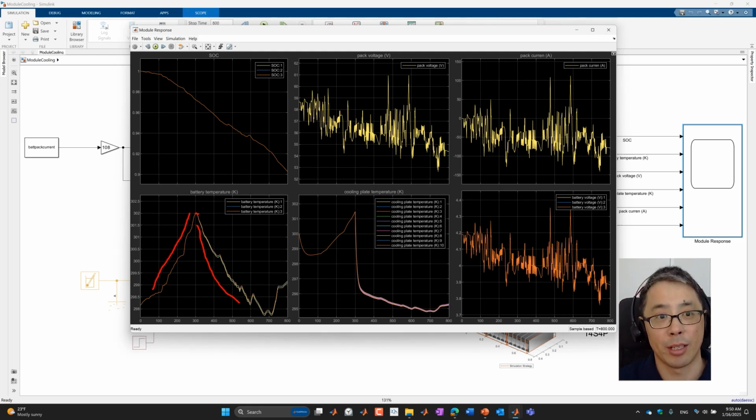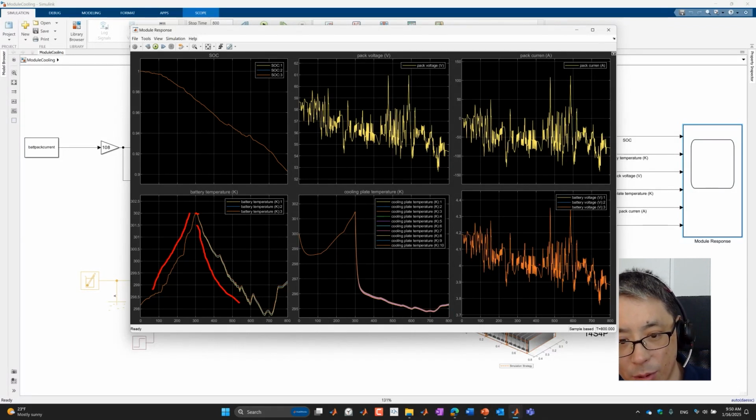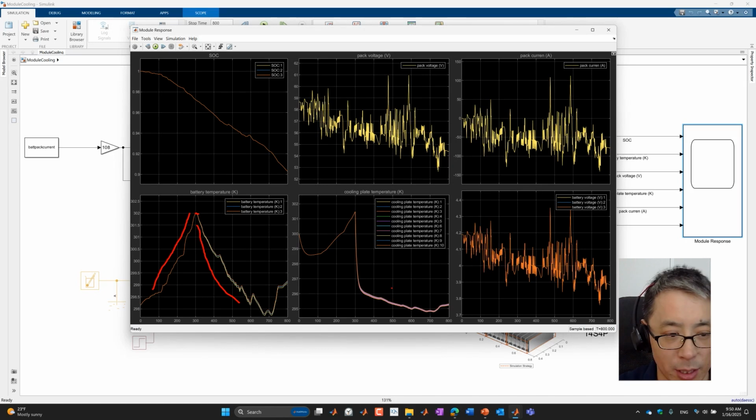So my controller here is manual. I just say turn on the coolant flow at this time, but in the real world system, there'll be a more sophisticated controller and mostly closed loop control. And then the middle plot is how the cooling plate temperature looks like, which is understandable. And then the bottom right is how the cell level voltage looks like. Again, there are 3 curves because our model is grouped resolutions and 3 models. So that's the simulation results here.